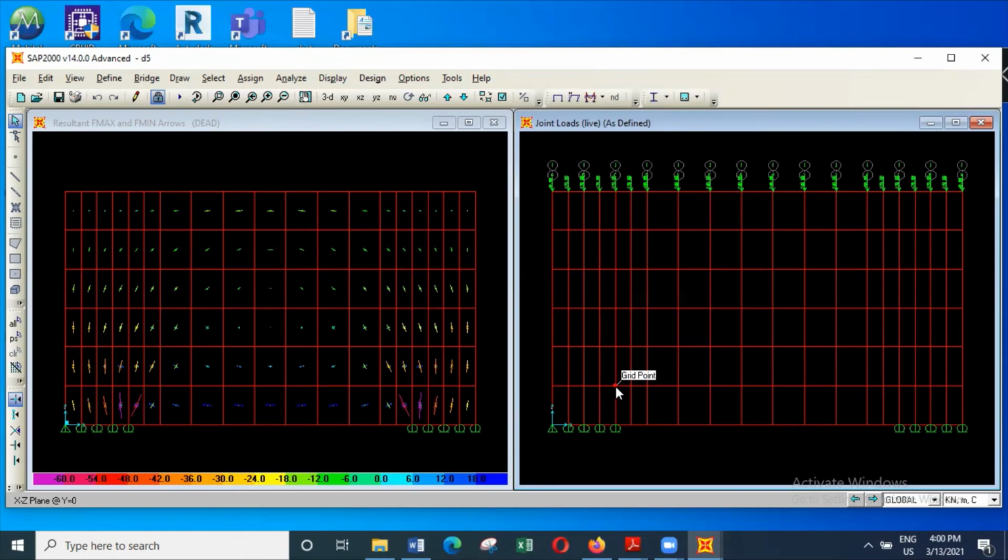So you can see a very similar wall, but the loads are different. Support conditions are different. So you might treat it slightly differently, because one has a small support where the rigid zone over the support may not be significant, whereas the other has a wide support where the rigid zone can be a significant portion, where we can consider the loads to be transferred directly. So we don't have to worry about those forces being transferred through a strut. Those can be transferred directly.